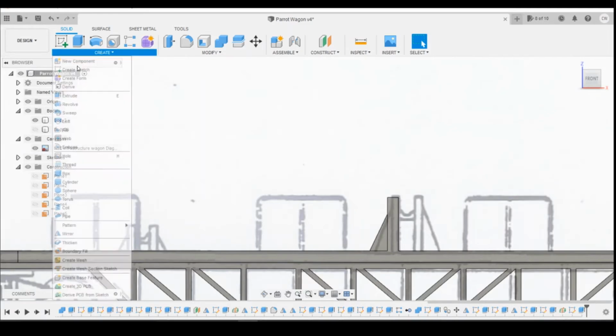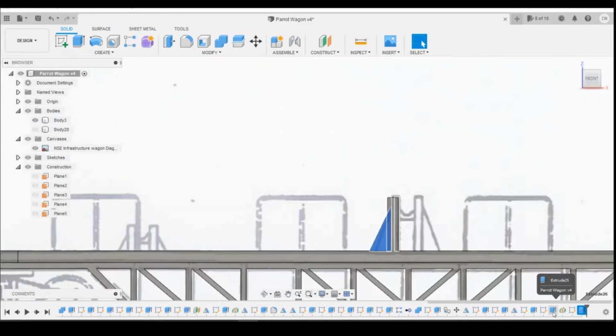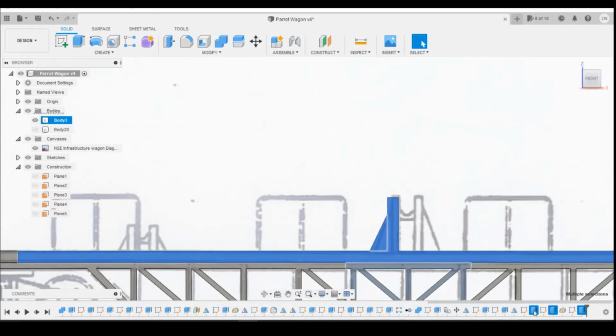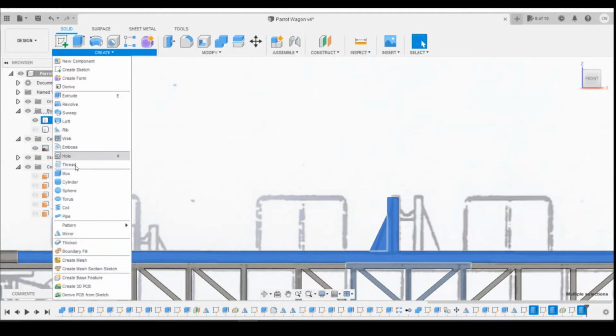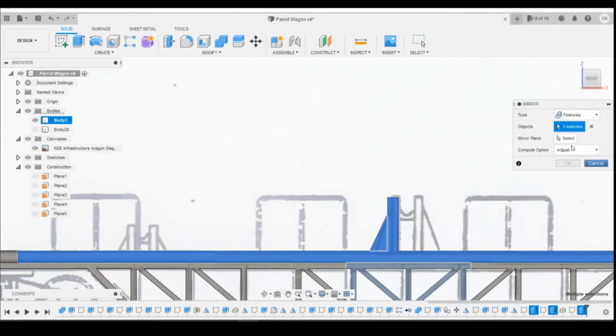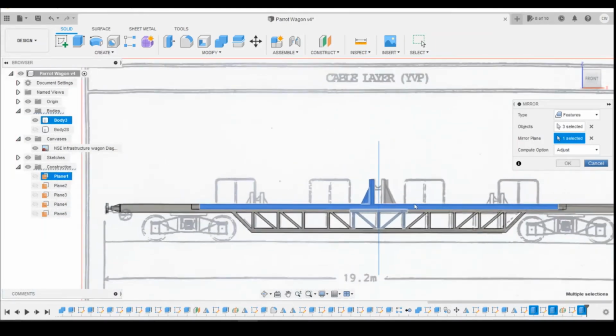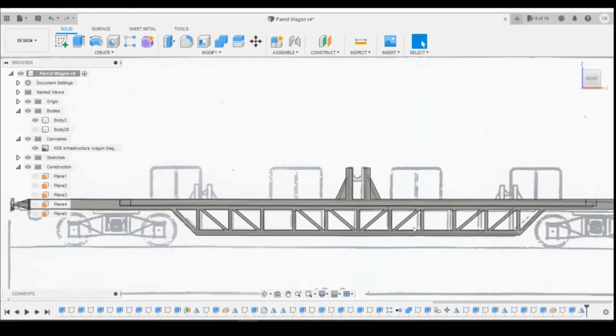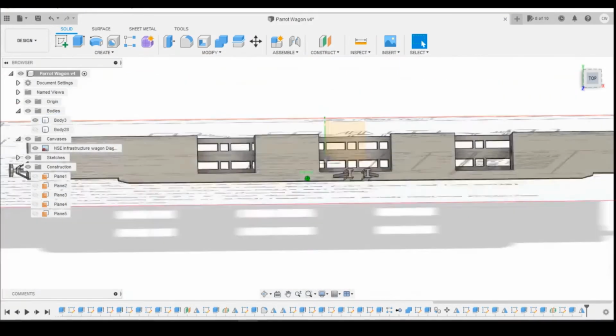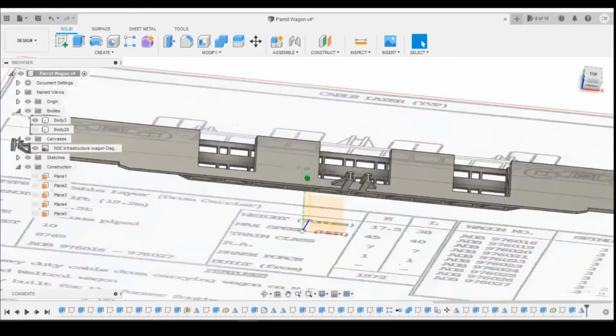We're now going to mirror that across. So we're going to select that plate, the extrusion and the upright. Why's the mirror gone off? We select that's a mirror. Those three features, mirror plane, and we want plane number 1 is on the plane. Okay, make sure nothing's copied over by mistake. No, that looks okay to me.